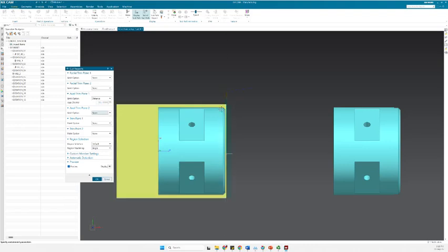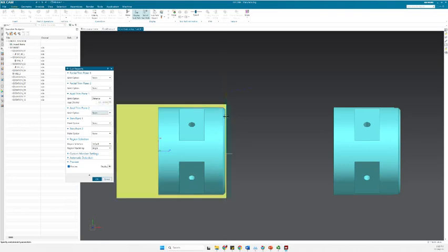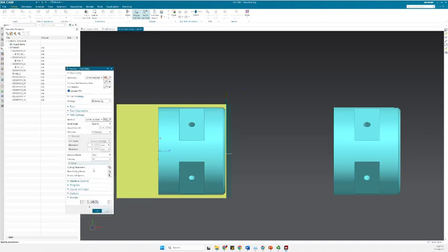And now it looks all right. It's actually left a bit of material for the finishing. If we would put 33, we would have even more material for the finishing, so 32 should be all right. We still have the material for the finishing aspect also. After that, we click OK. And anyway, this is the facing operation.